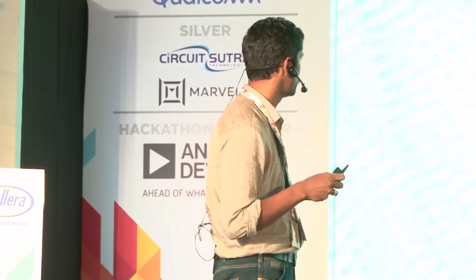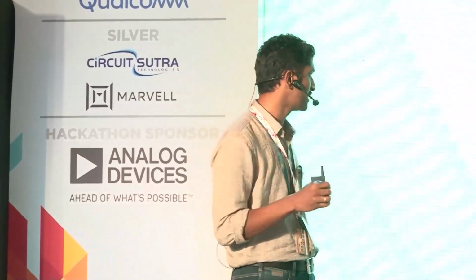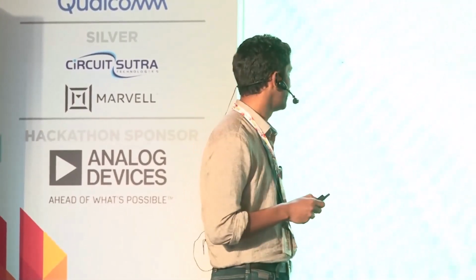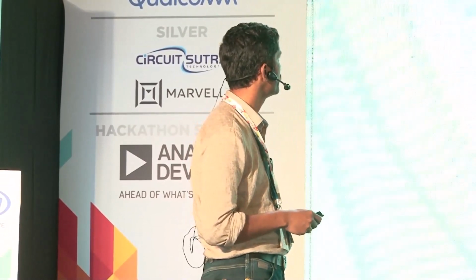So we had to educate the tool that some of the signals toggle at least once during the simulation. We had to add all such assumptions, and then we could start seeing the meaningful results.